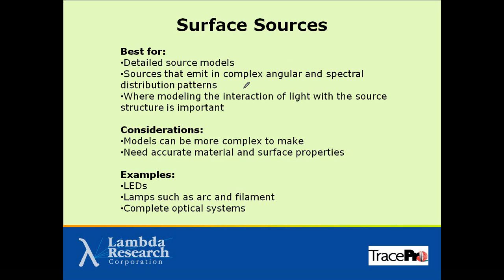So you can define a surface source property as having polar and azimuth angles and wavelength dependent emission. So you can model the spectrum of that lamp or that LED. Then you can start looking at things like true color and CIE coordinates and color temperatures in TracePro.